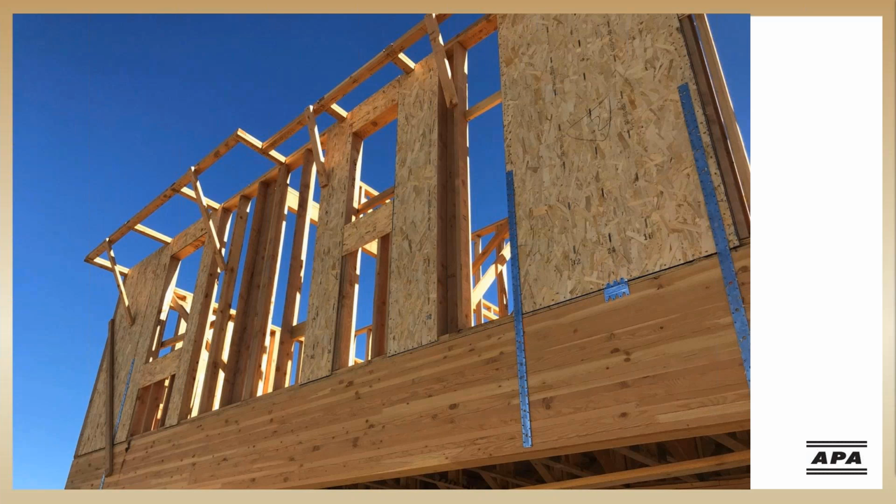Now, this is an engineered example, but I'm going to point out here a common constructability detail at the window openings. So you can kind of understand, the panel on the right appears to be right around 4 feet, so you've got that standard panel width and a couple more feet before we hit the sheathing around the opening. But the panel on the left runs right into the sheathing at the opening.